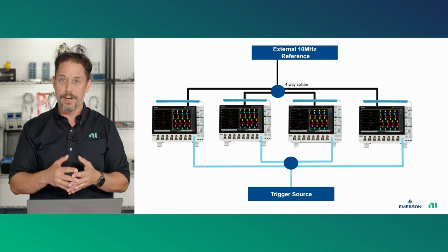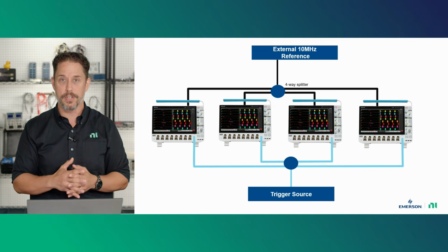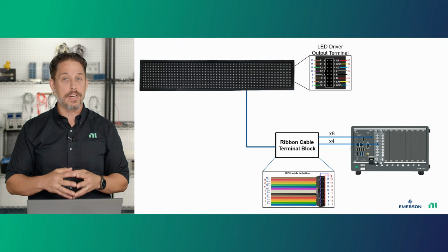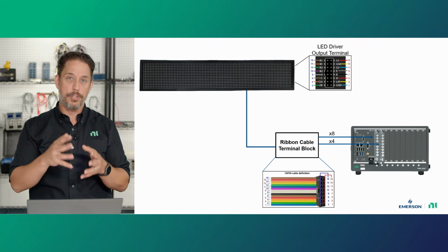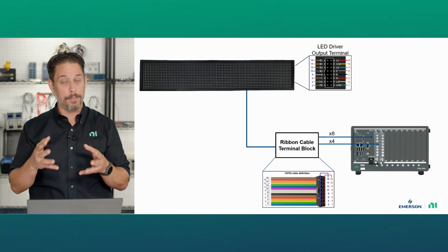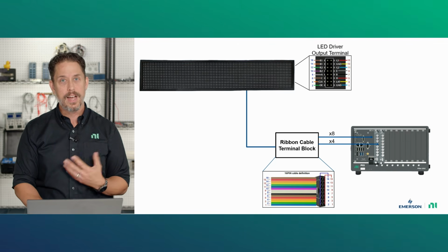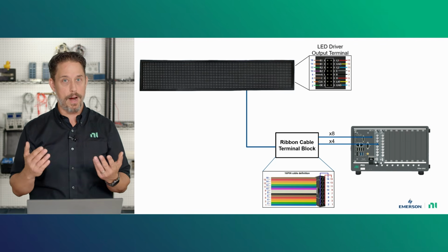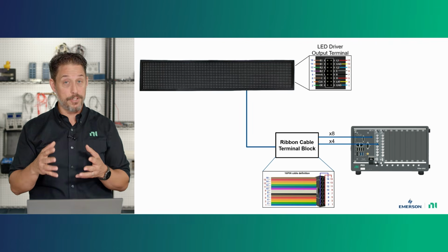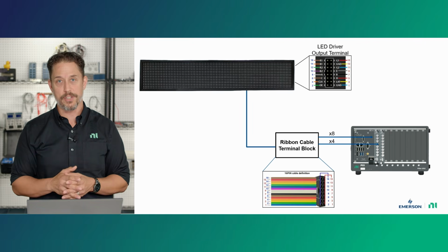And that's something that we know matters a lot to you as a test engineer, to make your lives that much more efficient. And so instead, we're going to use this setup here, where we have 2 8-channel oscilloscopes in our system, and then we're going to hook up to those 16 lines coming off of it, and we're going to automate that with the driver.